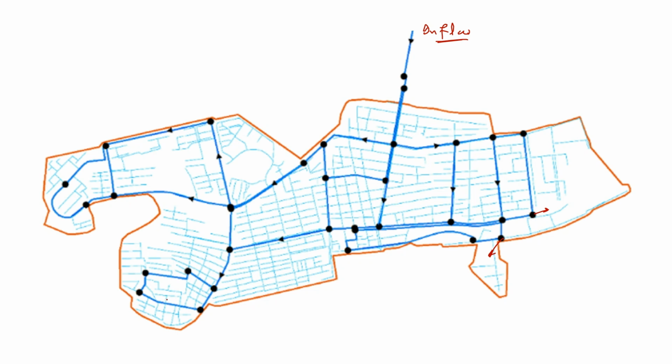All the blue pipes you can see here, we will need to distribute this inflow in these blue pipes using the Hardy cross method. So basically, you can say that the Hardy cross method is applied to distribute flow rates within pipes of a pipe network or a distribution system. But for the Hardy cross method to apply, we basically need closed loops. Here you can see that this is a closed loop of pipes. There may be three, four, minimum three pipes, and maximum we have no idea how many pipes can be there in a closed loop.